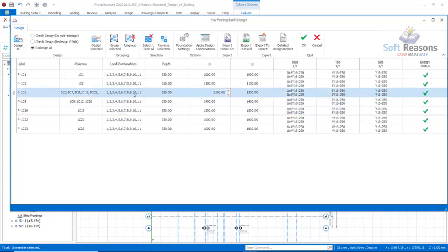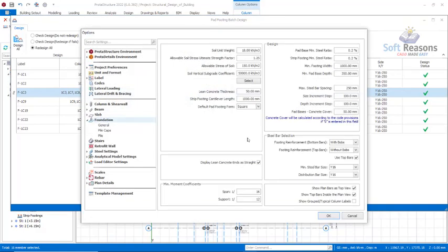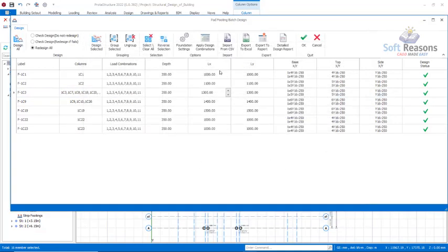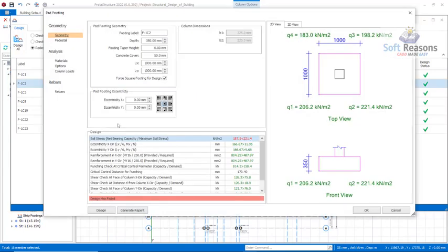So in each of these groups, like the 1.3 group, you can now select it, and then you'll be able to select the property to edit. As in, you can now edit the parameters. Okay, I mean to make sure you edit the footings' rebars detail, as in you can decide whether you want to have a double reinforced pad footing or a single reinforced pad footing. Okay, by double clicking on this.